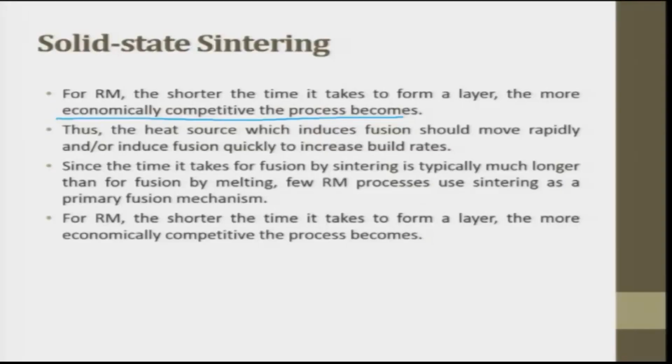So, you will have to apply more heat, and when you apply more heat, it takes a longer time for making the parts. Thus, the heat source which induces fusion should move rapidly or induce fusion quickly to increase the building rate.